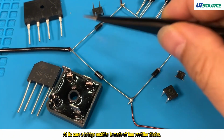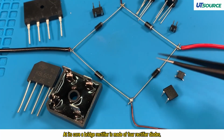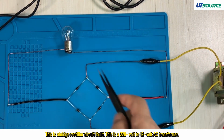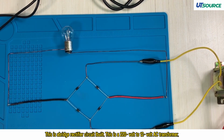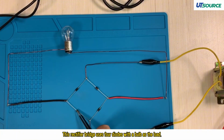At its core, a bridge rectifier is made of 4 rectifier diodes. This is a bridge rectifier circuit built. This is a 220 volt to 12 volt AC transformer. This rectifier bridge uses 4 diodes with a bulb as the load.